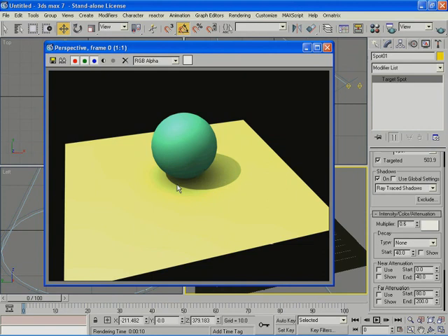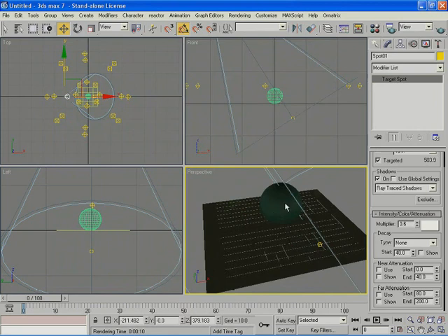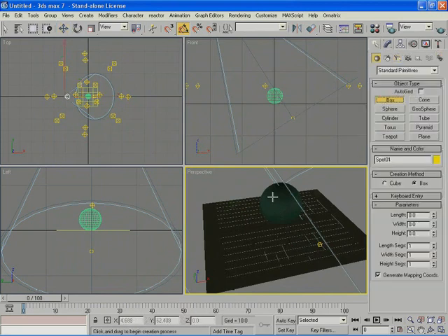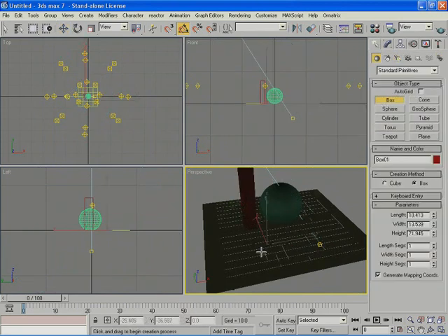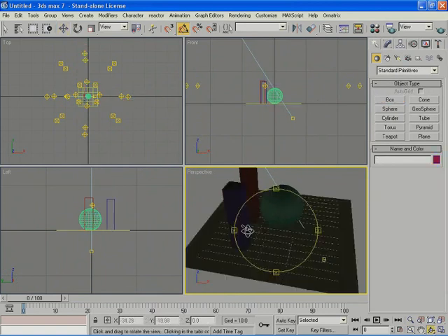By using this technique, which is a fake global illumination technique, we can get faster results, and we also get ambient occlusion, which is the fact that we are getting these shadows underneath the object. Now, the good thing about this is that whatever you place here is going to get the required shadowing. So if I go here and do a render, everything will have those nice shadows underneath it.